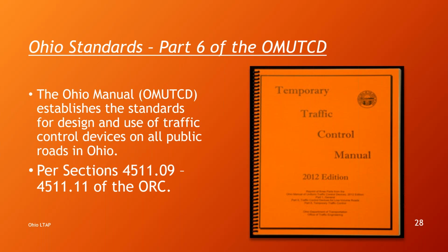The other side of that is that if there's a crash in your work zone, that could be the basis for a lawsuit. If you don't have it set up correctly, your agency might be sued by whoever was in that crash. So it's another important reason for you to know that. You should never just go out there and wing it with your own design of a flagging operation. You need to set it up the way the manual tells you to set it up.